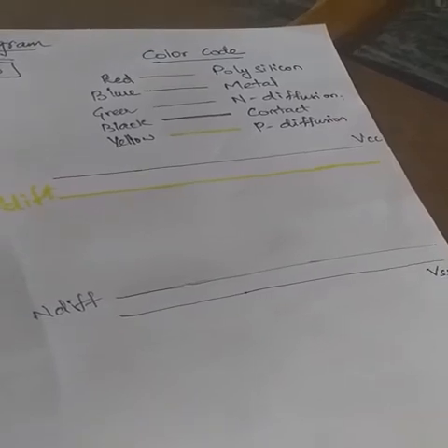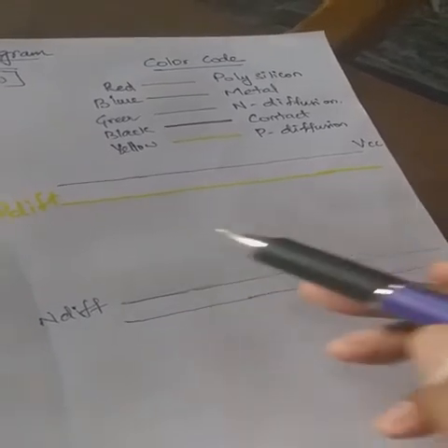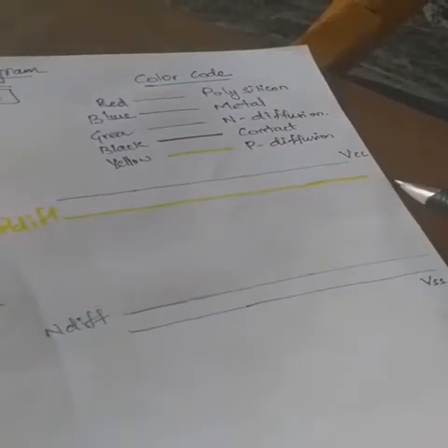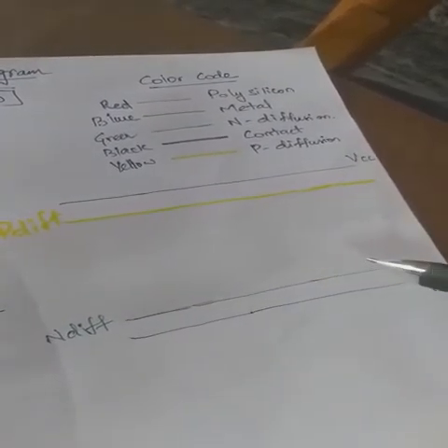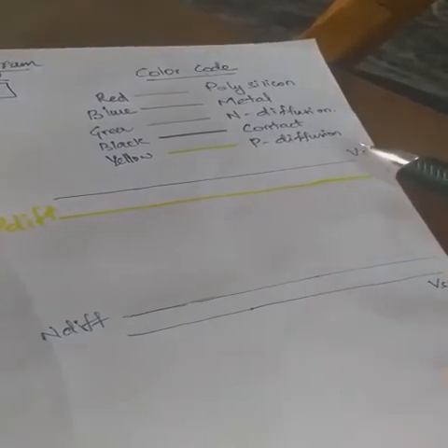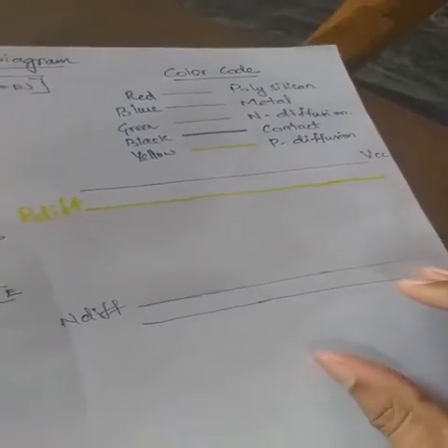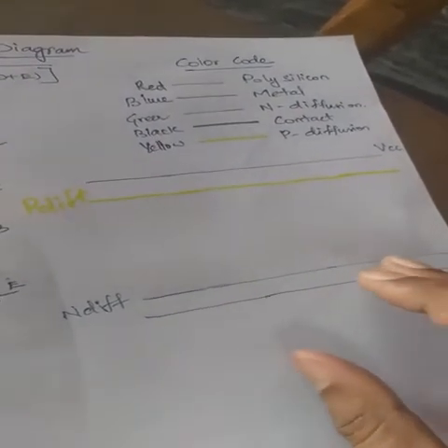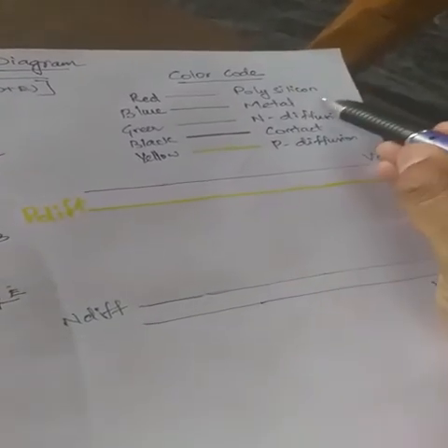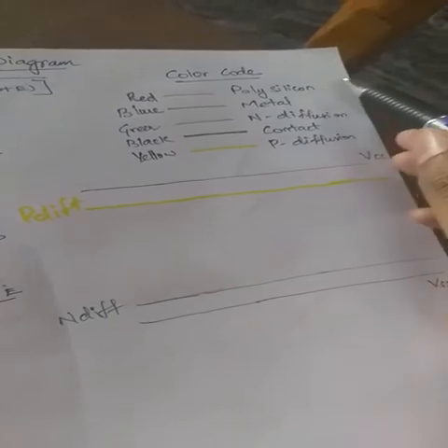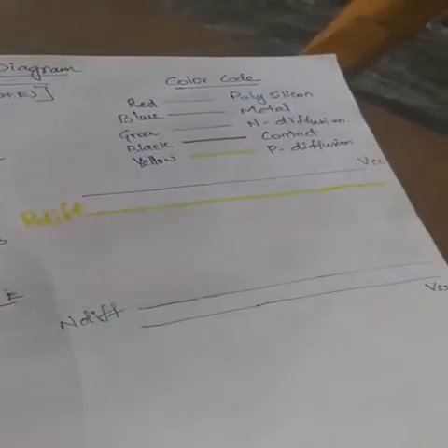The next thing you have to draw is the polysilicon layer. We have formed the substrate material, the P-type substrate and the N-type substrate. Next we have to form the transistors. How many transistors? We have to draw 5 NMOS and 5 PMOS transistors. Transistors are formed whenever a polysilicon line crosses a diffusion line.